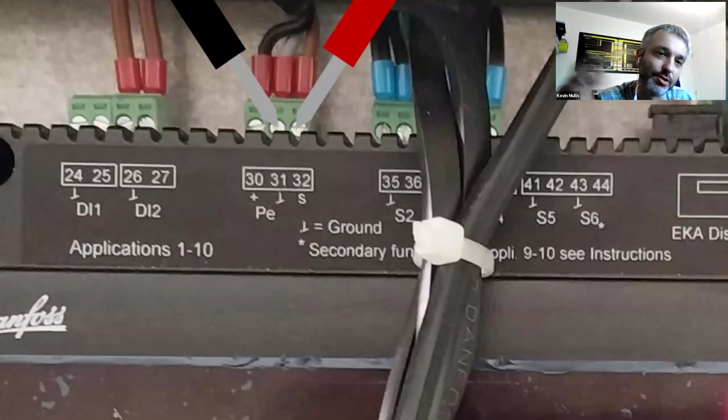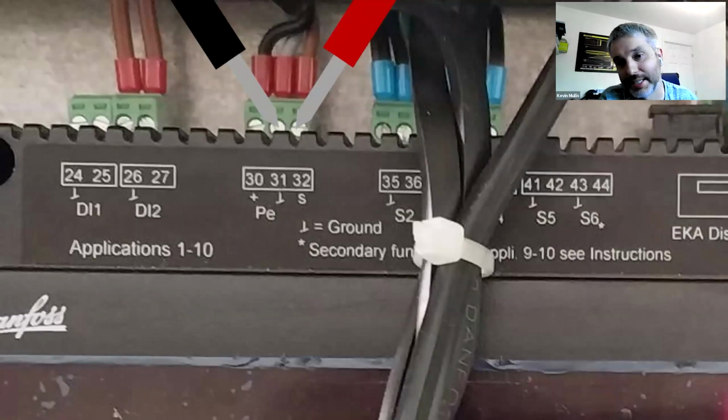And depending on what you set your transducer range to in the controller and what gas you select, it will give you your pressure and your calculated temperature from that. So if, for example, it's not running and you've got 5 volts where you've got the probes there, that would be maxed out on the transducer. So you've either got a system that's stopped and your pressure is very high, or you've got a fault somewhere or a missed wire.